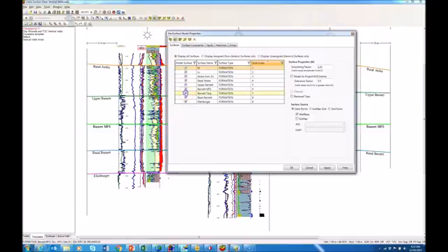And it looks like right through here between the maximum flooding surface and the basal Barnett, this would be our good target surface. So let's add a target surface to our geomodel. Target surface right there. Turn on our surfaces, make that the active surface, and use our picking tools to pick where we want this to be. Now I'm using our new Quick Picks mode. This is new for 2015.0, which will allow us to very quickly pick tops.